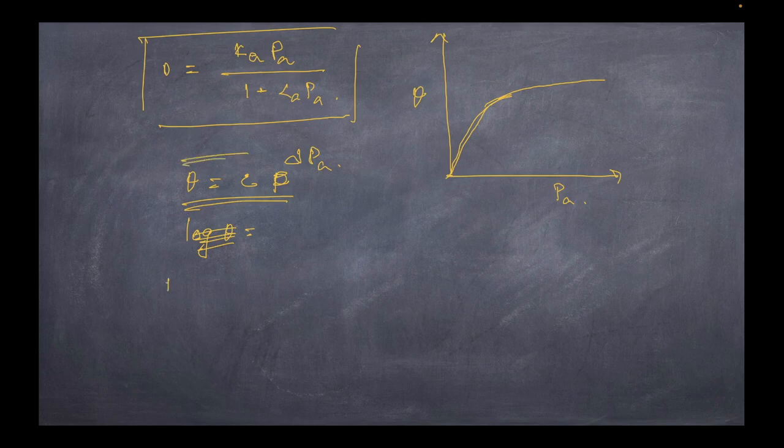Okay, so let's now consider the BET equation. This is a modification of the Langmuir isotherm model. In the BET equation, multilayer adsorption is considered. The gas molecules are first adsorbed as a monolayer on the surface site, then other gas molecules can interact with these gas molecules and adsorb over each other. Now the heat of adsorption between the first layer and the surface is, let's say, delta H1, and the heat of adsorption between the second layer and the first layer, and the third layer and the second layer, are all equal, which is the heat of liquefaction.